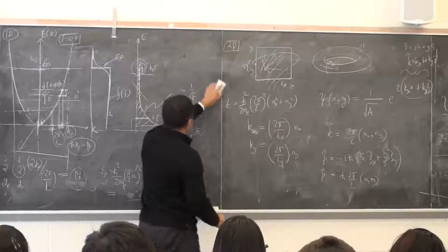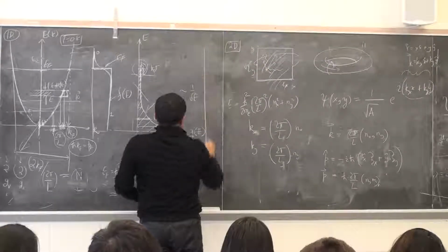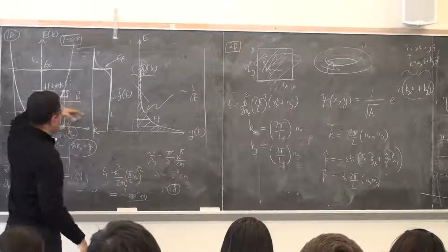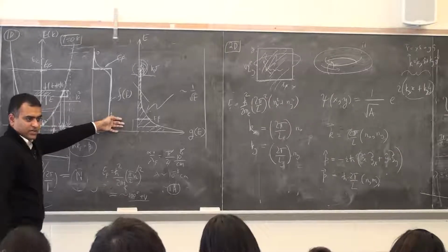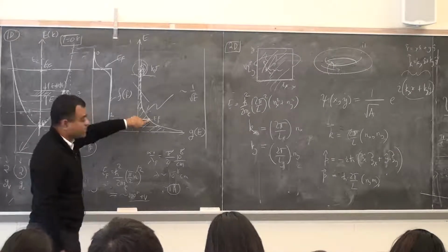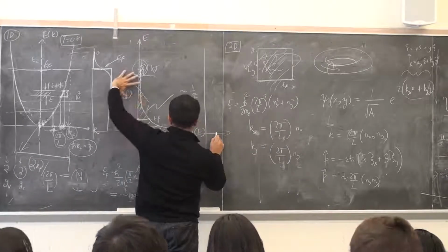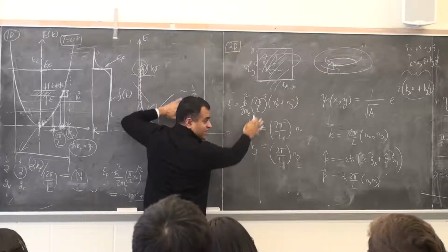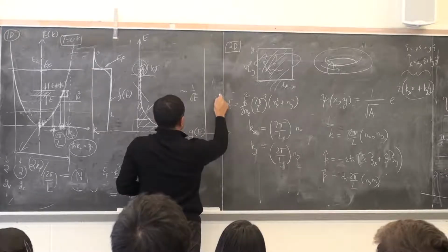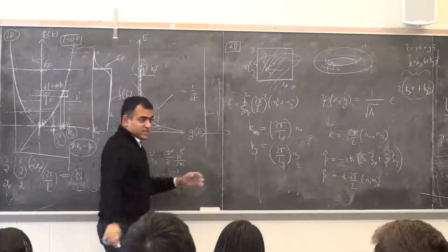In the next class, not on Tuesday, but on Thursday, we are going to again apply all these things and ask what is the density of states now for 2D? And we'll see it will not be 1 over square root of energy. It will be a constant. And that's a very important result. We'll see the density of states by using this E-k diagram. You can evaluate it by yourself. It will be a constant. It doesn't depend on energy.